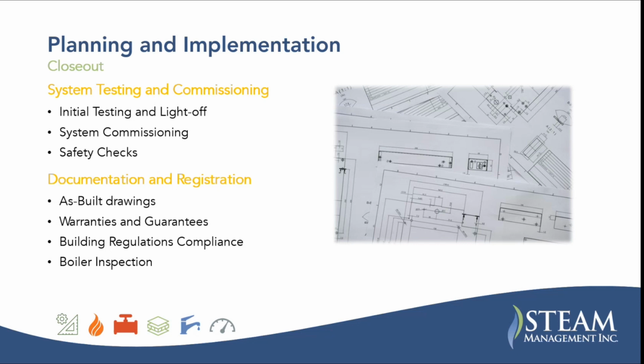So you're going to revise your drawings, or your contractor is, for as-built. Make sure you have all your documentation in place for your warranties and guarantees, and make sure you're submitting everything for compliance with building regulations, and for your boiler inspector, and have him out to inspect the installation.